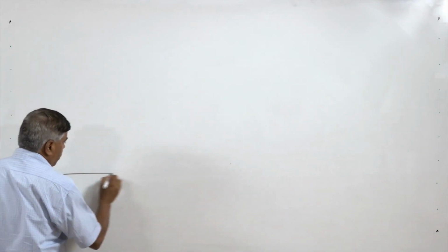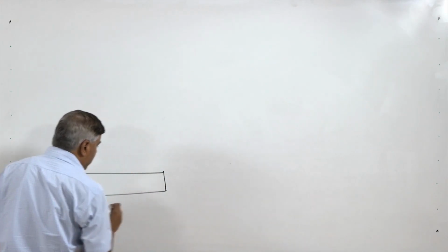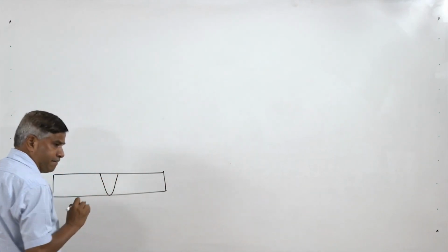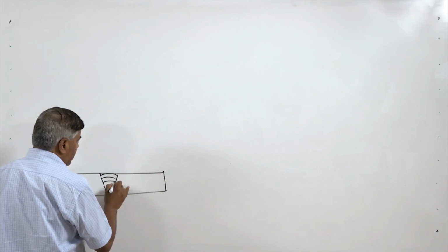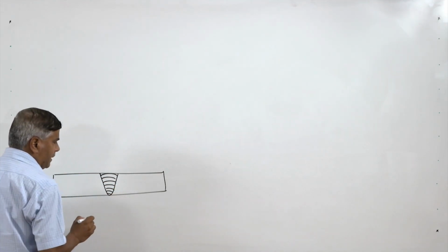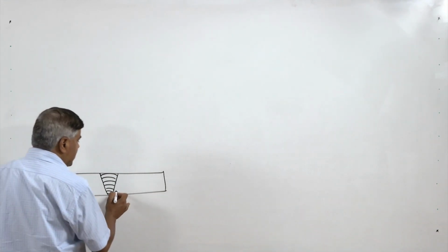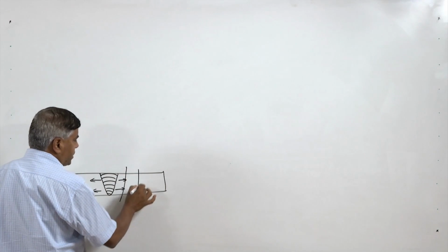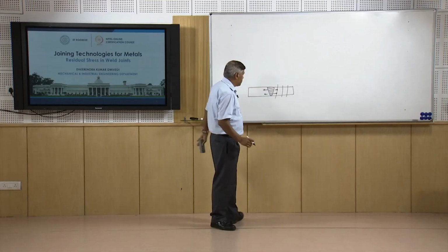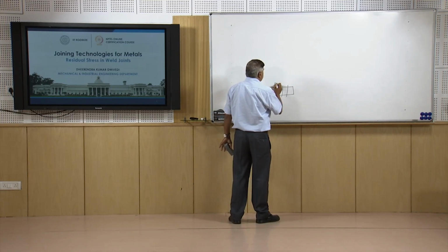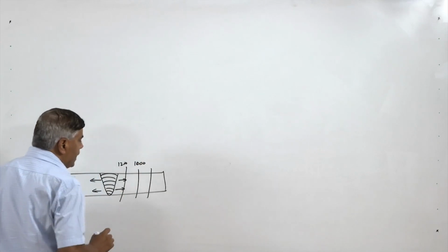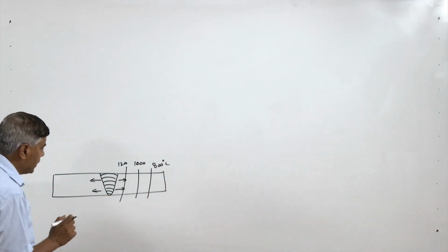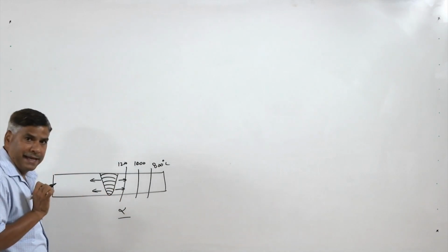seeing. So, for this what we need to see is that in any welding process, any fusion welding process, what do we do? We apply external heat through a suitable heat source for realizing the fusion of the faying surfaces or edges of the base metal. So, in the course of this, heat is dissipated to the base metal also. So, the different regions are subjected to different values of rise in temperature. Say this one experiences a temperature of 1200, this one experiences 1000, and this one experiences 800 degrees centigrade. So, we know that if all are made of the same metal, alpha is the same.